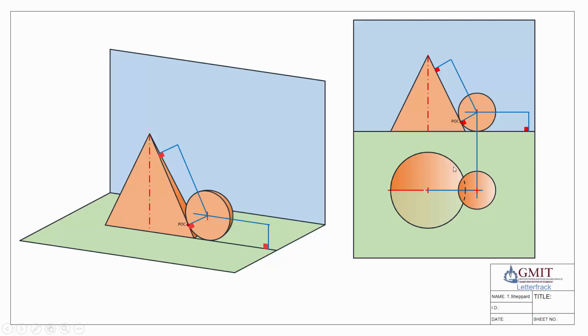And just to show you as well, if you look at the hidden detail here, some people are surprised when they start off: why don't the two solids appear to be just two circles touching at one point? Well, because there's an overlap. Because this is a cone, this solid here is leaning in over the base of it, so there is going to be this overlap like so.